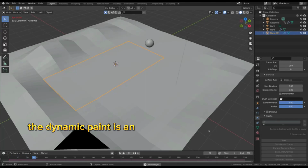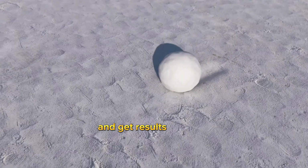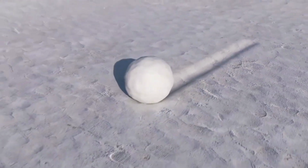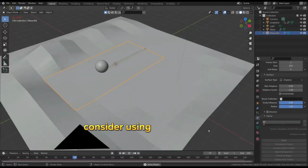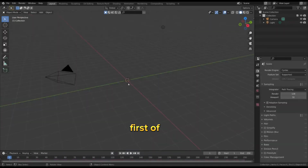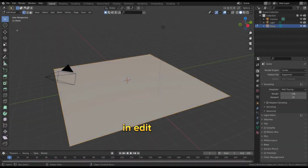The dynamic paint is an easy way to draw on a canvas and get results like this. So every time you need to draw a footprint on the ground or leave a footprint on a surface, consider using this technique. First of all, let's add a plane and subdivide it in edit mode.